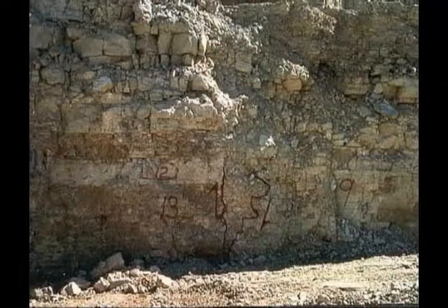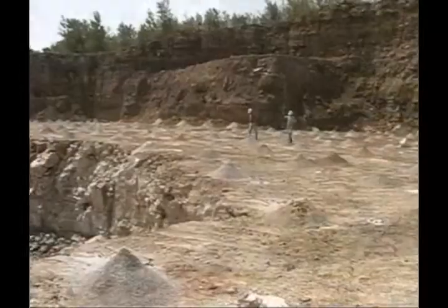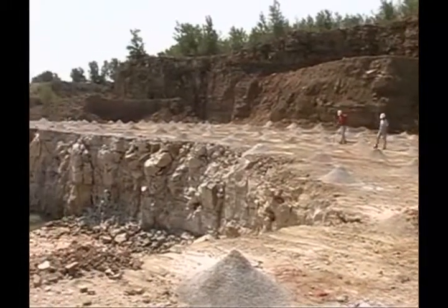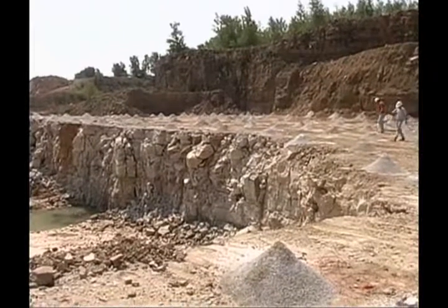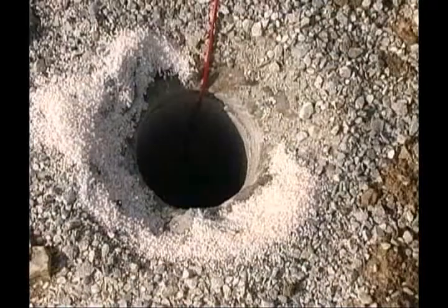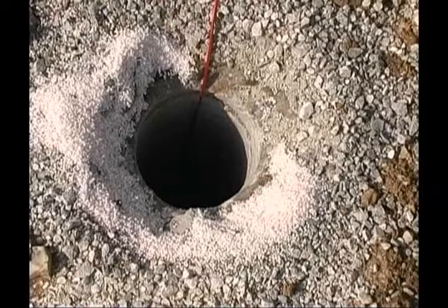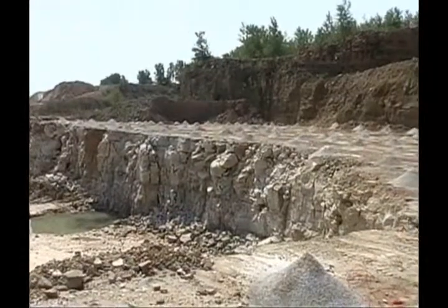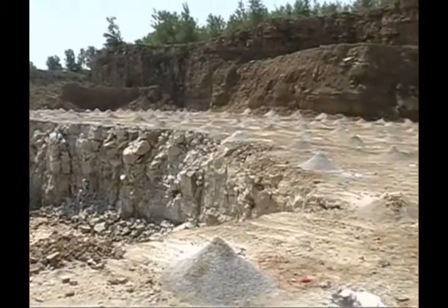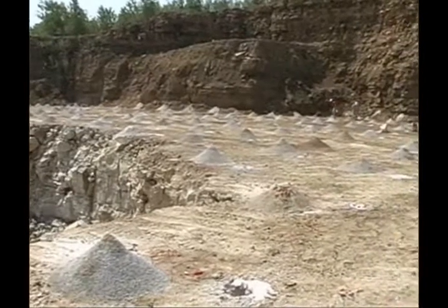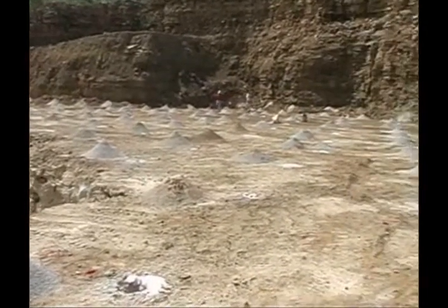Care should be taken if dipping beds, faults, or clay and mud pockets are present. Once the desired beds are located, the beds above may need to be removed. The working ledge will be drilled to the desired depth. Be sure the material is not drilled and blasted to more than the approved depth, as material from below the ledge may not meet specifications.